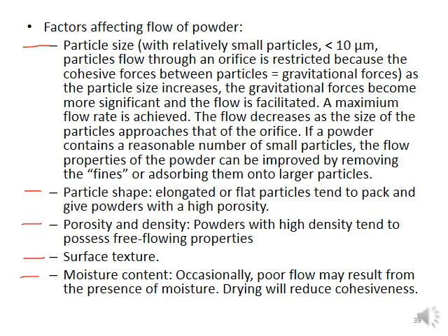In this case, cohesive forces equal gravitational forces. When the particle size is increased, gravitational forces facilitate the flow. This is true as long as the size of the particle is smaller than the opening. Flowability can be improved by removing fine particles that are extremely small, or by adsorbing these particles onto larger particles.